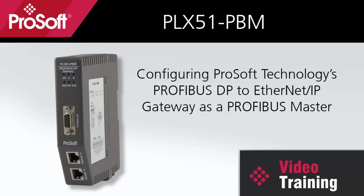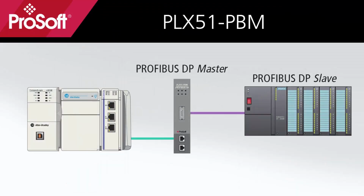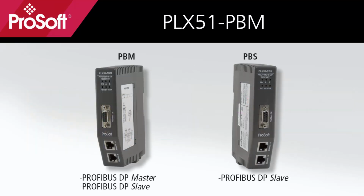Today we're looking at the PLX51 PBM gateway configured as a master on a PROFIBUS network, allowing a PROFIBUS slave device to communicate with a CompactLogix processor on EtherNet/IP. The master setup is only available for the PLX51 PBM module, while the slave configuration is available for both the PLX51 PBM in multi-slave mode and the PLX51 PBS.